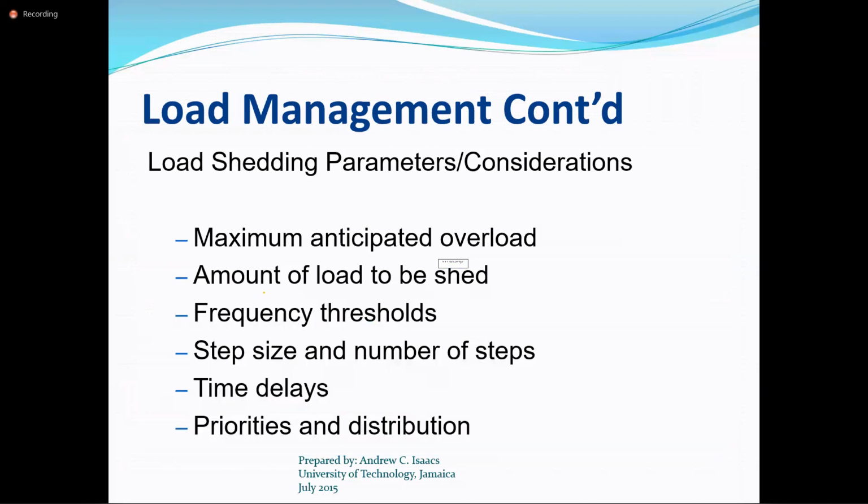And then finally, some of the considerations for load shedding. You have an overload, the amount of load that you need to shed. You have frequency thresholds, time delays, priorities, and distribution. So in other words, we can shed load.